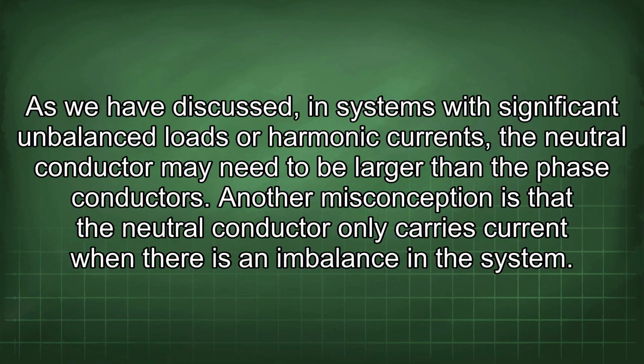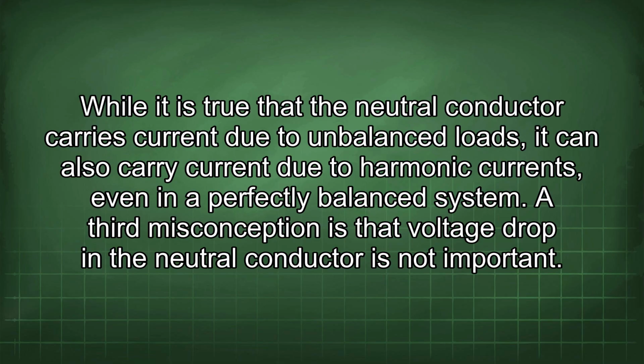Another misconception is that the neutral conductor only carries current when there is an imbalance in the system. While it is true that the neutral conductor carries current due to imbalanced loads, it can also carry current due to harmonic currents, even in a perfectly balanced system.